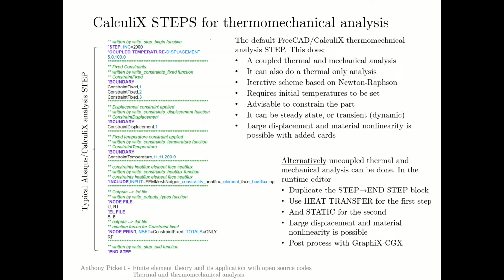Now, I will be showing you how we do that with CalculiX, but in fact, by default, FreeCAD will write out the thermomechanical analysis in such a way as to activate a certain option which is called coupled temperature displacement.